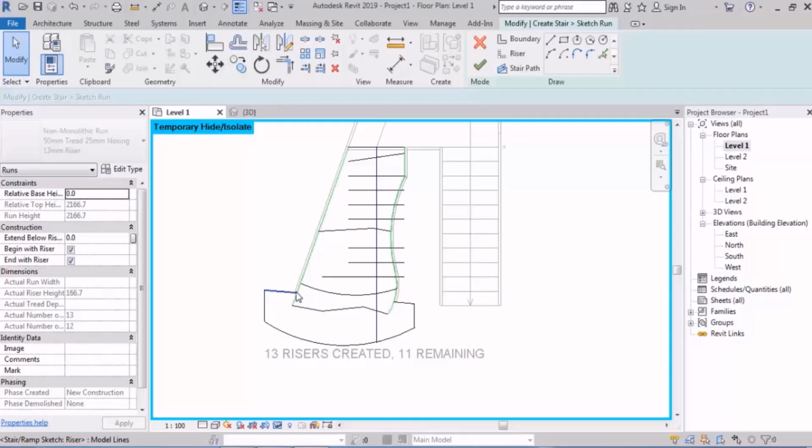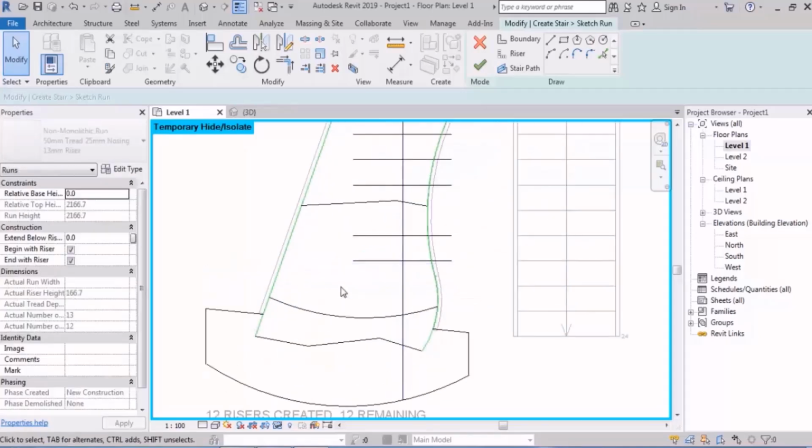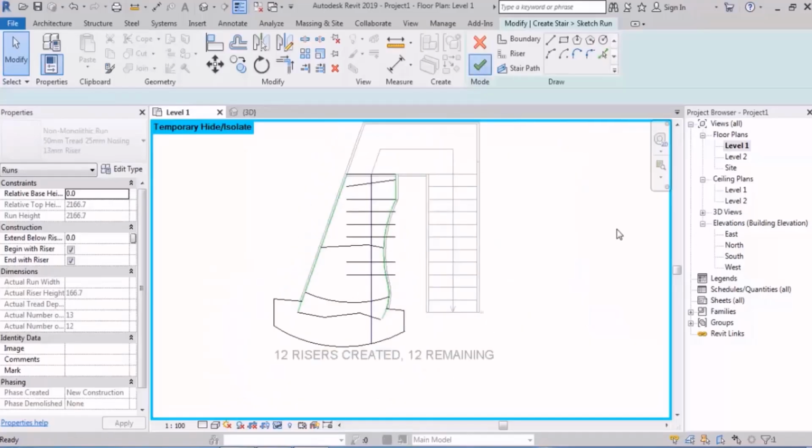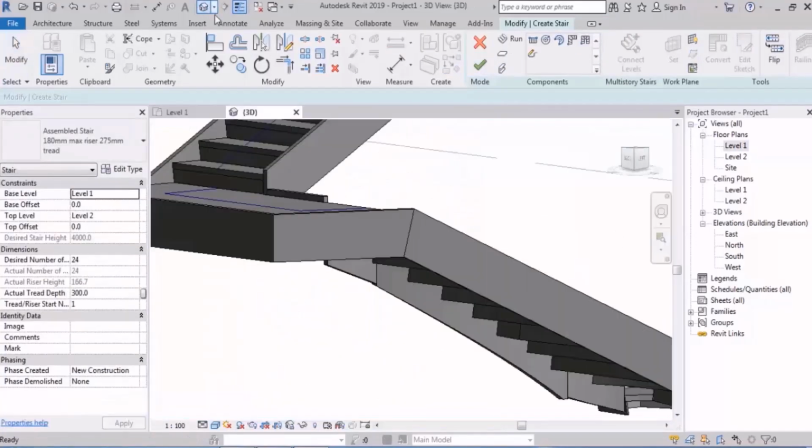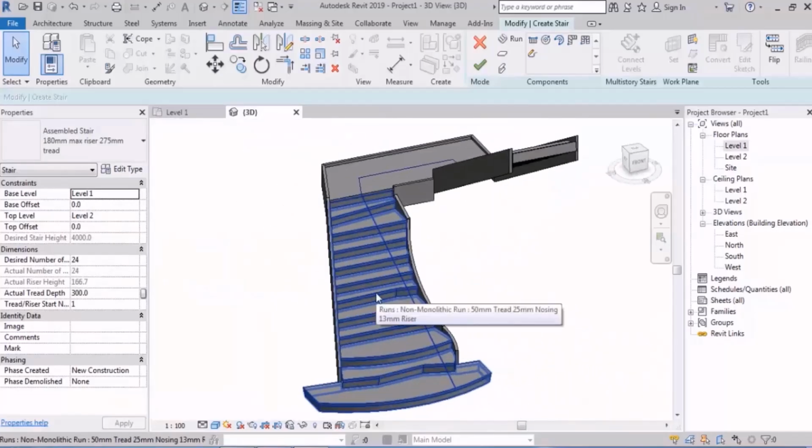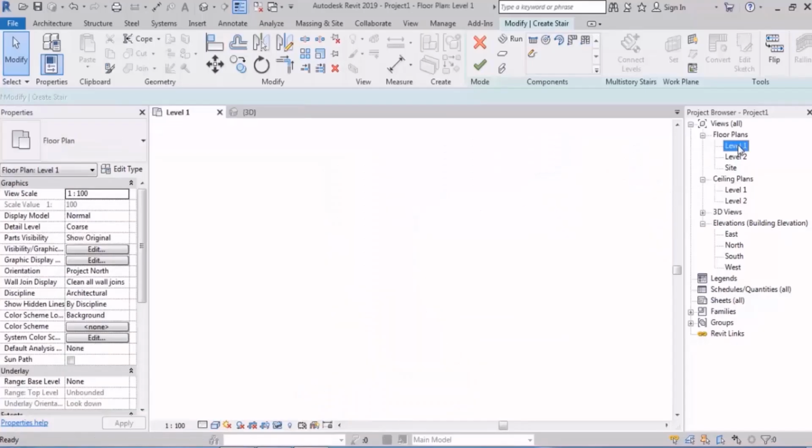Alright. So adding a riser can also lead to error. The connection with the landing is now gone. But we can fix this. How? How can you fix it? Well, we delete this one instead. And when I click on finish, not only will we face the unjoined message, but also it will be fixed. So it's possible to fix the stair and the risers when we click on unjoin and it doesn't get upside down. It actually happens a lot. You're in the middle of editing and something goes wrong, but you can fix it.